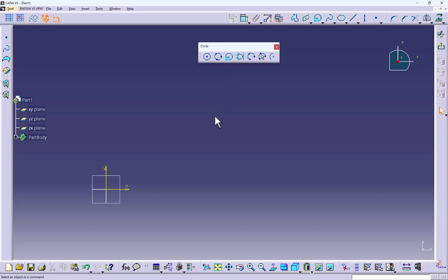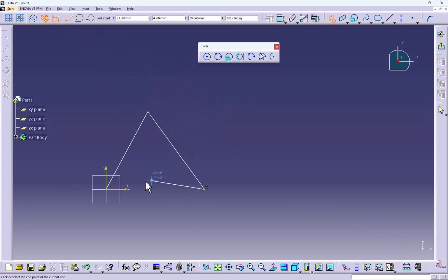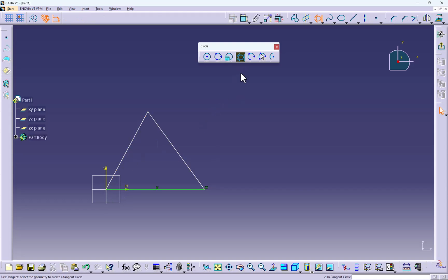Next, we want to make 3 tangents anywhere and we want to make a circle. We can create 3 tangents and we can create a circle. Let me get back to line. So we can click on this tool 1, 2 and 3. We can get the 3 tangent thing. This is how we can make a 3 tangent circle.